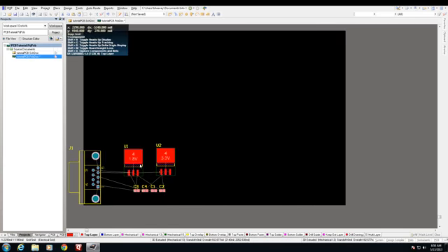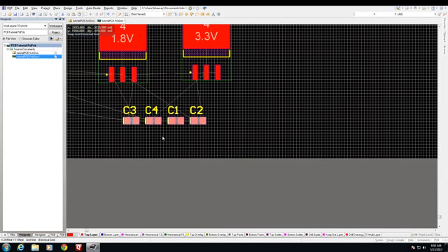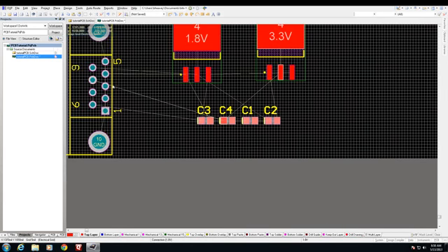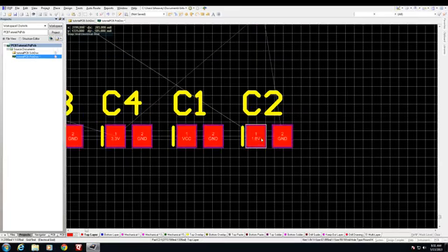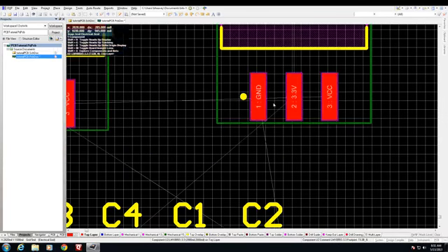I'm going to go ahead and zoom in a little bit more. You'll see all of these wires, or rather these lines, which indicate how the components should be connected. So I scroll or zoom in a little bit more, you'll actually see the net labels on the components.